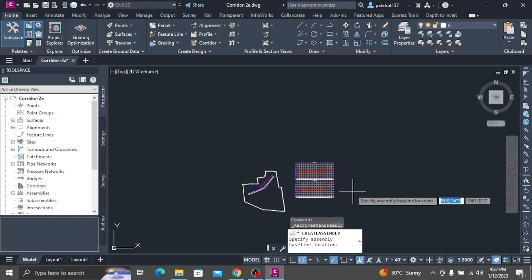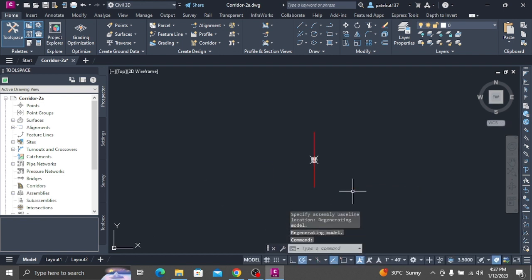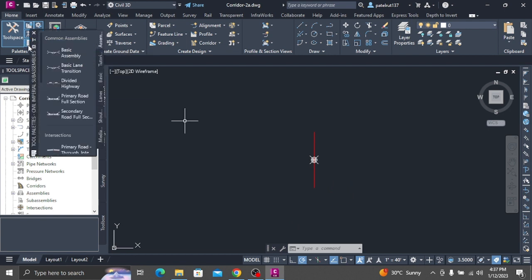In the Tool palette, click Basic Curb and Gutter. In the Properties palette, under Advanced, specify the following parameters. Side, right. Gutter width, 1.2500. In the drawing, click the marker point at the top right edge of the lane to draw the curb and gutter. Add a sidewalk subassembly.